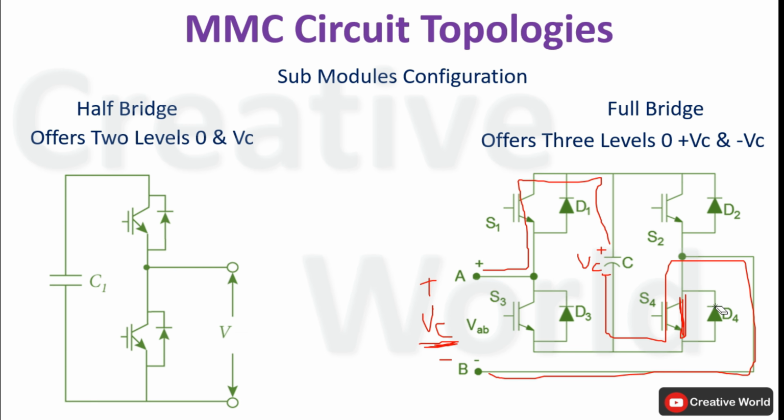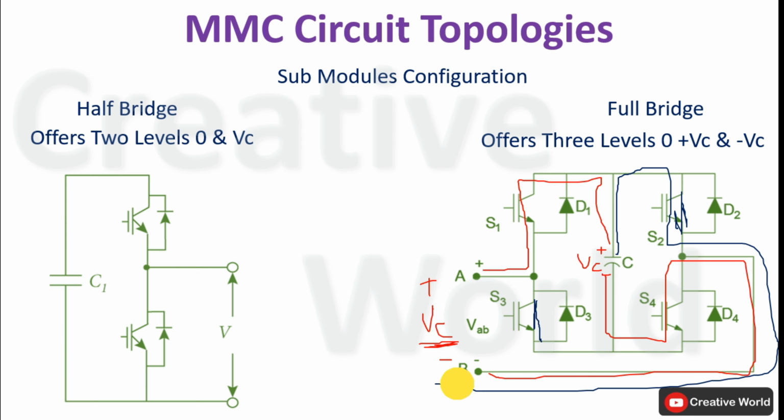Now imagine these two switches are opened while the other two switches are closed. So these two switches are closed. In this case the path will be completed in this way. At this point B, positive VC is appearing, while on point A negative VC is appearing. Now in this case we are getting negative VC with respect to this polarity, because on the positive terminal we are getting negative voltage and on the negative terminal we are getting positive voltage. So this is the second voltage level which is retrieved from the full-bridge configuration.